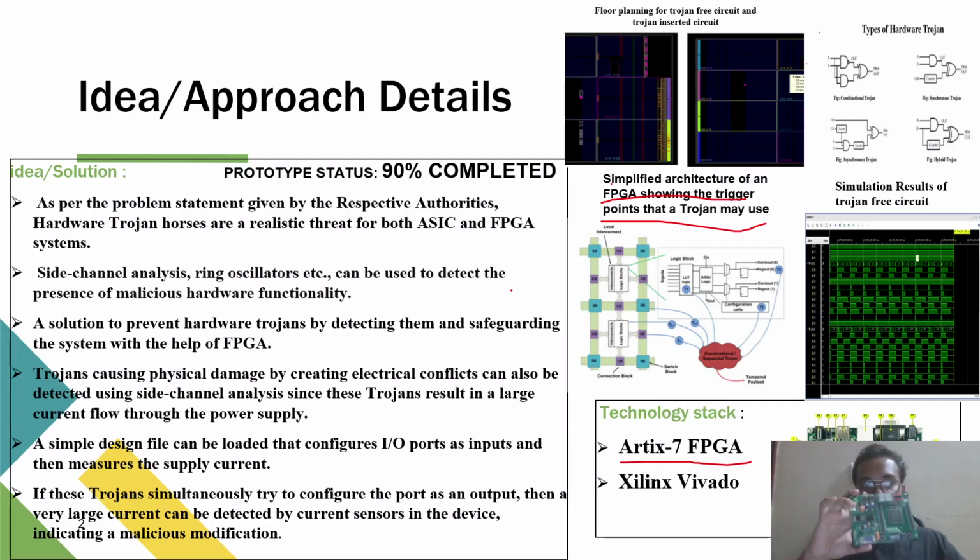At high temperatures, one logic gate will behave according to one temperature, so temperature-based logic gates will operate. Because of that, to identify the Trojan, the remaining logic gates will get damaged. So this destructive approach is not encouraged. What we want is an easy, non-destructive approach.